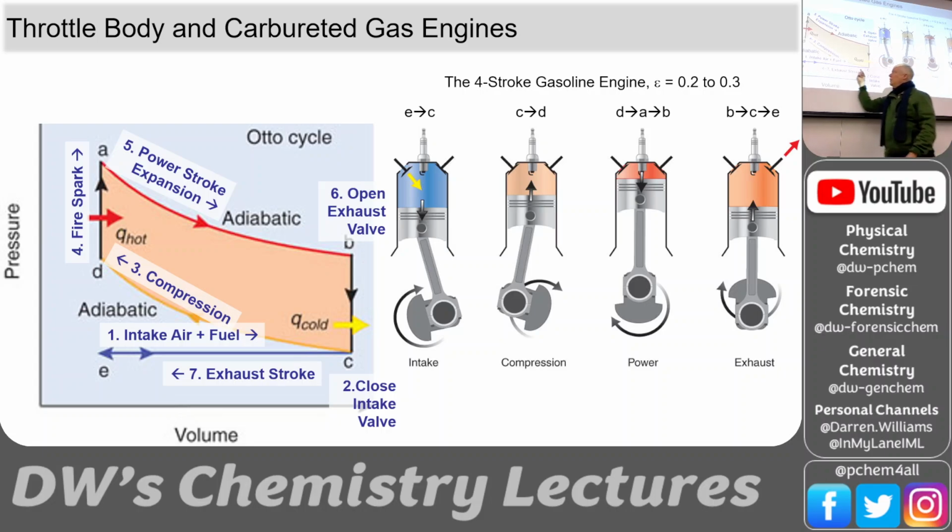We suck in with the piston coming down, we go through the thing, and then we push the gas out by the piston going up. So we're just exchanging gas on the intake and exhaust strokes. And then 1 stroke is a compression stroke with the valves closed and the explosion. And then you have the power stroke, the valves are still closed, so you can have that power.